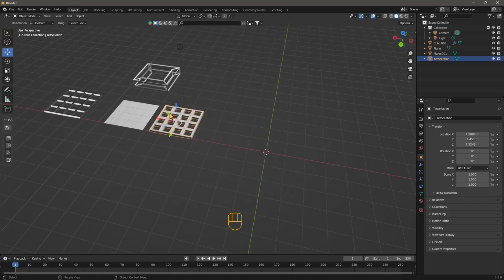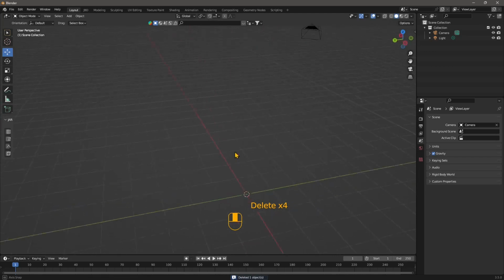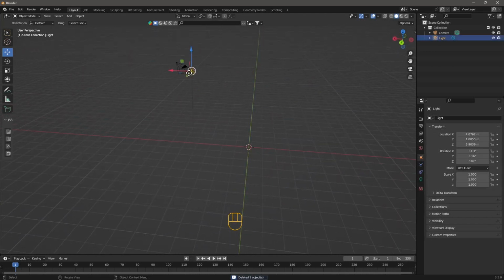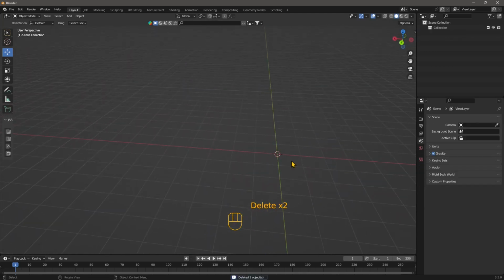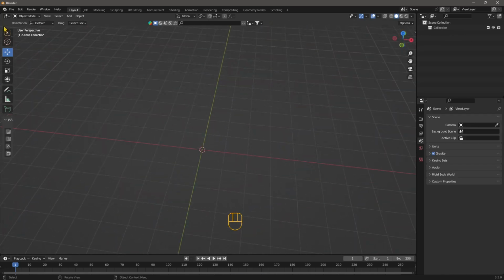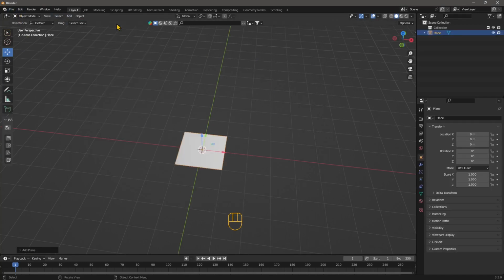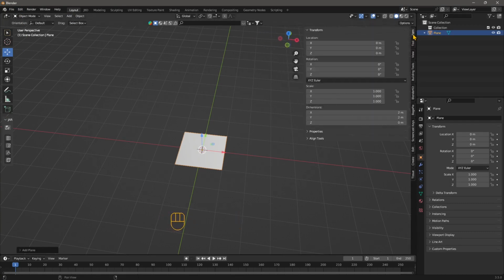So the first thing we're gonna do, I'm gonna delete here. We're gonna see the easiest way we can create these effects, and then we will also use some more advanced features. So the first thing I want to do is a quick wireframe. So what I can do here is go to Add, Mesh, and let's add a plane. Now I want to rotate this plane around the X, so I can also expand this sidebar and go to the rotation, choose the X, and if I want to do this precisely, I can type 90, so I have a perfectly frontal plane.